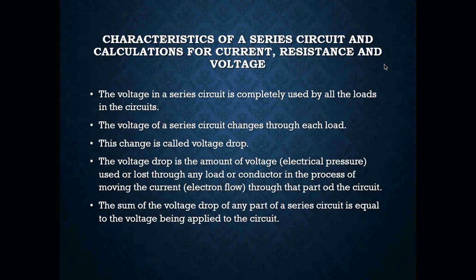For example, say you have two loads wired in series and they're both using 60 volts of electricity. 60 plus 60 equals 120 volts. You should have that total at the end.